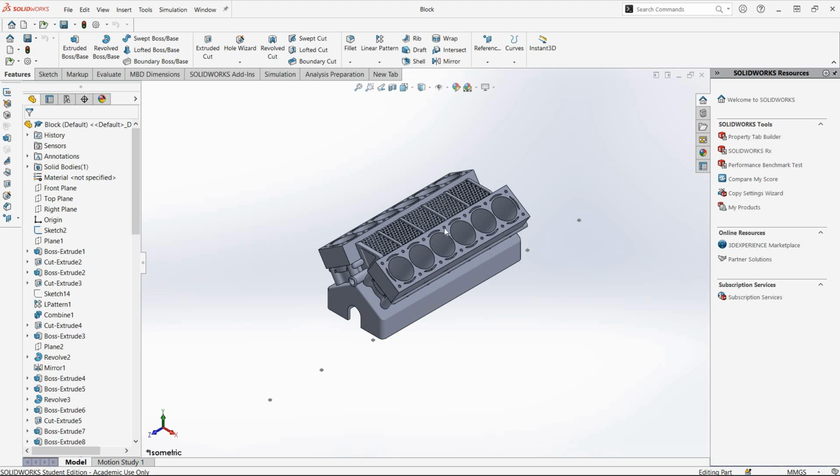For starters, I squared off the top of this block for more stability. Furthermore, what he had in his design was an open deck, which essentially, as you see these slots here, they were not connected to the cylinder. So essentially the cylinder was kind of free, which is not good, as it causes lots of disturbance and vibration, and it would probably cause the engine to pull up, so I ended up going closed deck on that. Which, anyway, is better that way.